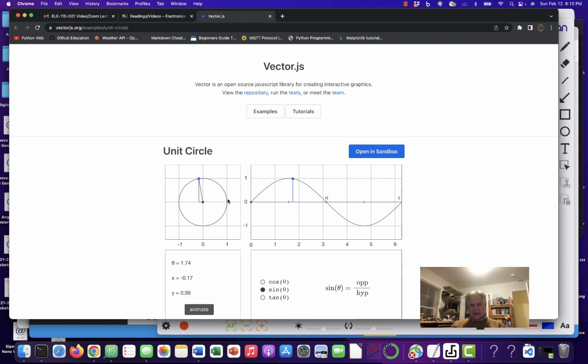It's called a phasor, and this phasor thing is important. If I'm starting here, like this is time 0, see the time down here at time 0? If I swing through 0 at time 0, then my phase is 0 degrees. In other words, I swing through 0 at time 0.